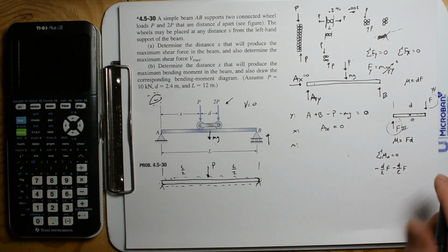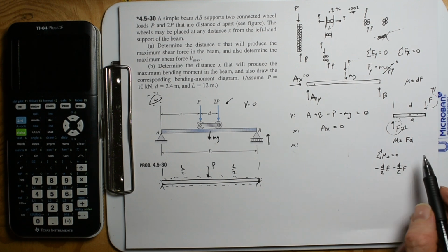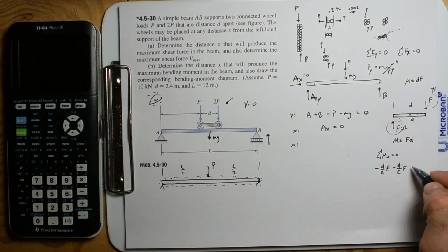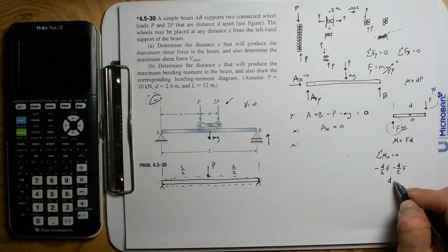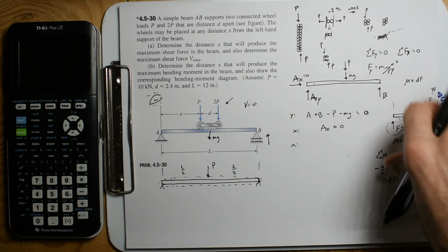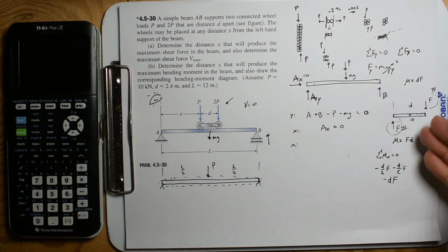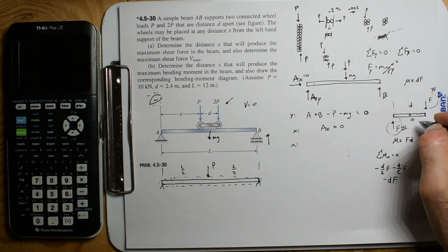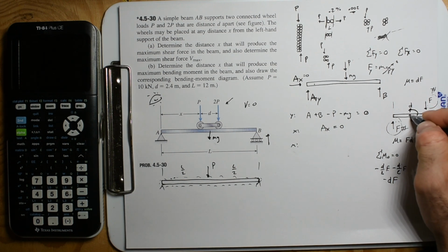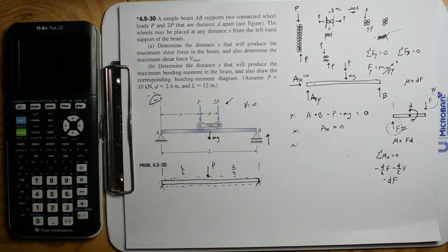So we have this is the moment: d divided by 2 times F minus d divided by 2 times F. This is just negative dF. So we have the magnitude of the moment is dF, and it's in the negative direction. Cool. So we have to balance that with a moment in the opposite direction. And so we could just apply a moment. You know, I mean, we could attach something right to the middle of this.